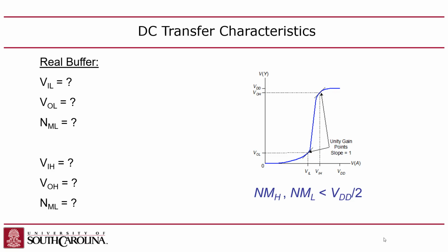I'm increasing the input, and it barely goes up. And then at some point you're going to hit a magic number, the transistor threshold voltage. At that point, it zooms up really fast, and then after it zooms up, it sort of levels out.